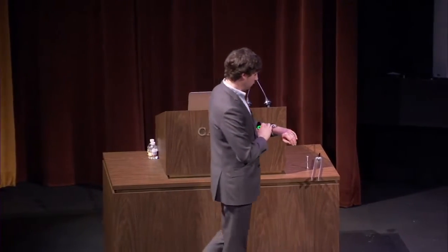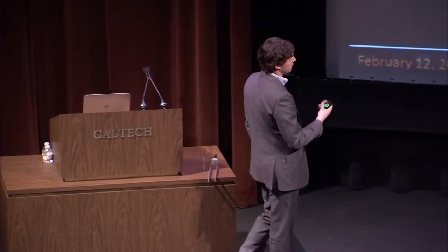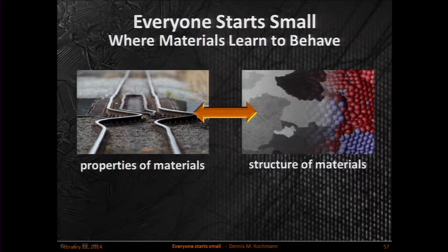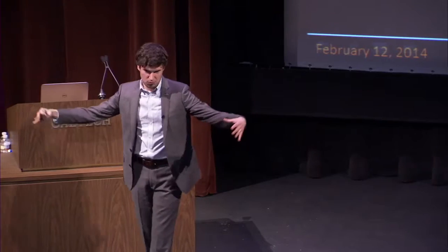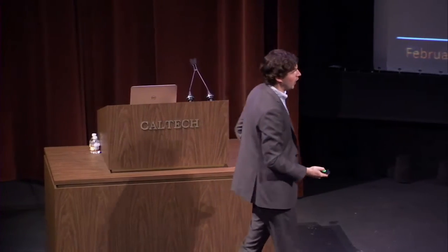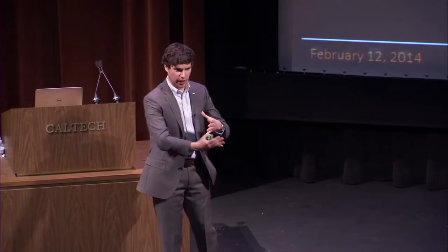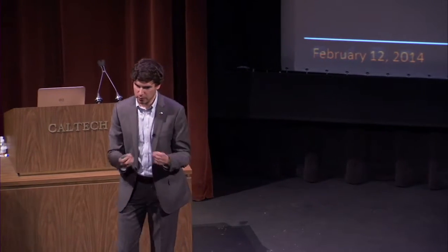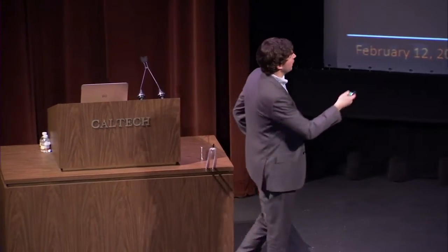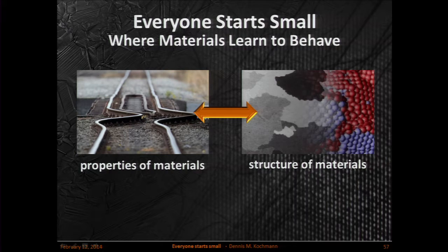So what I tried to show you today is how structure and material properties are related. We talked about how the crystal structure of individual atoms leads to performance, to stiffness, to lateral expansion, what we call Poisson's ratio, to density, to weight of metals, why metals behave the way they do. We talked about why and how they can deform permanently. They form defects that move, that interact, and eventually, of course, they fail. You may have voids that coalesce and grow, and then you have a crack, and then it fractures. These are all ways how the structure influences the properties.